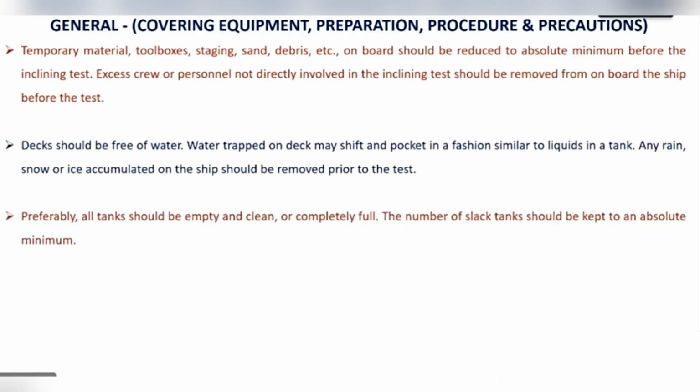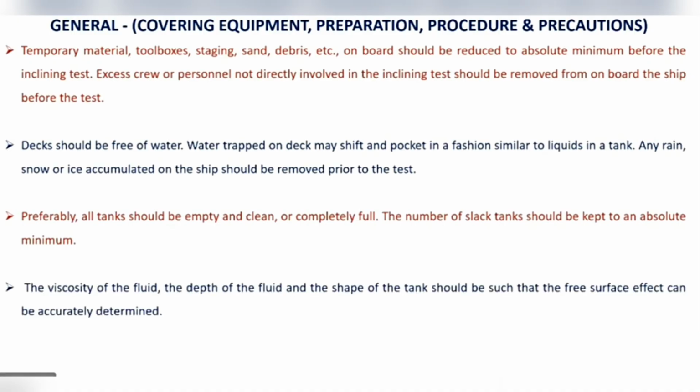Preferably, all tanks should be empty and clean, or they should be completely full so as to minimize the free surface effect. The number of slack tanks should be an absolute minimum, whatever is unavoidable. The density of the fluid in the tanks and the sounding of those tanks should be taken so that you can exactly determine the amount of liquid, whether it is bunker or water ballast or fresh water. You can exactly determine the weight of the liquid in those tanks, whether full or slack, because those weights will not be part of the light displacement. So you will need to know those weights precisely.